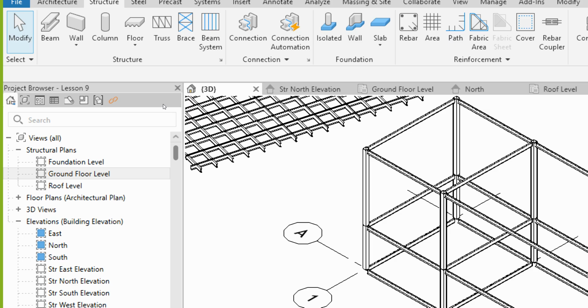So when we are building, we don't have the money to say I'm going to take 6 months and then finish a 3-bedroom house. No. People can do a foundation first. And when they do the foundation, then they go for another loan from somewhere and they come and do the superstructure. So it is always advisable, when you are modeling, to have this mindset so that you can model in different sections. So that when you want to face the project, you can face it: the foundation phase, the superstructure phase, the second floor phase, even the block work. Let's do the foundation phase first so that you can always segregate them and manage them properly.